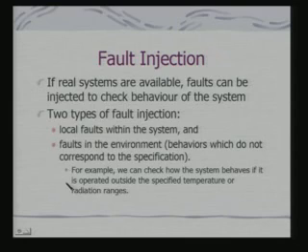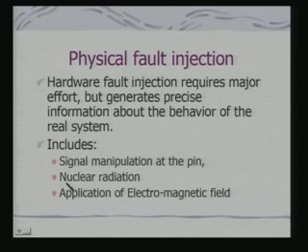Typical hardware fault injection would mean signal manipulation at the pin. So, what am I doing? I have designed a system, and now I am trying to inject faults into the system. You can manipulate signals at the pin. You can apply an electromagnetic field or nuclear radiation and see, these are all hardware kinds of fault injections, and see how the system behaves.